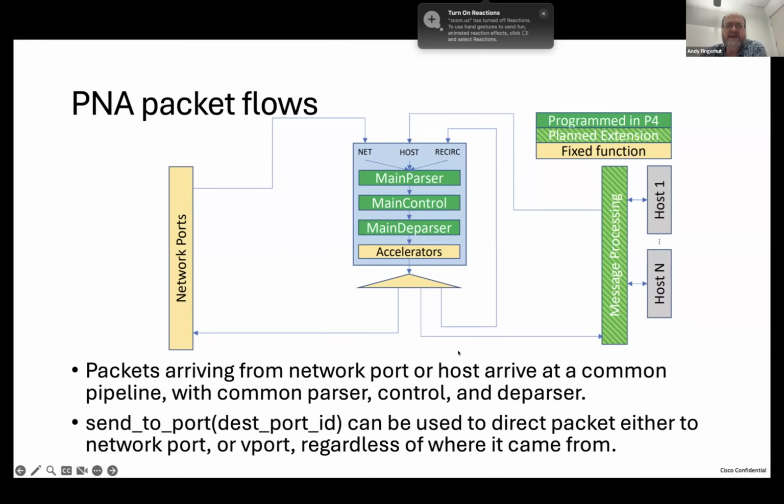One other question: do I expect smart NIC vendors to implement multiple P4 pipelines per NIC, as is the case for Tofino? Yes, someday, when the total bandwidth through a NIC is large enough that it is difficult. The main reason to have multiple pipelines in Tofino and any other chip is that 1 packet per clock cycle through a pipeline is about the maximum. It's much easier to develop 2 pipelines that are copies of a 1 packet per clock cycle pipeline than to develop 1 pipeline that's 2 packets per clock cycle. So basically it depends on the clock cycle and the packet rate you want to achieve, whether you want more than 1 physical pipeline.